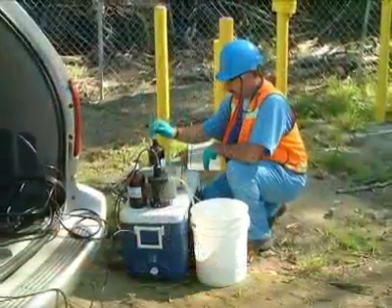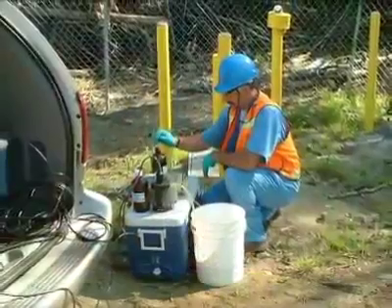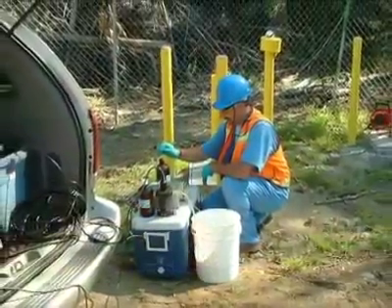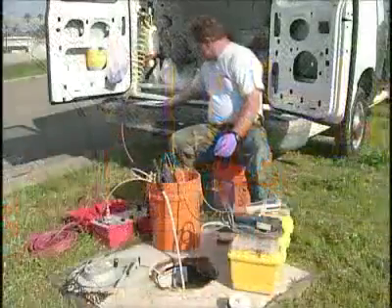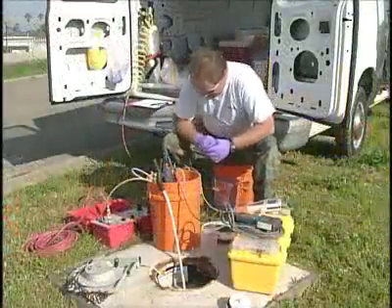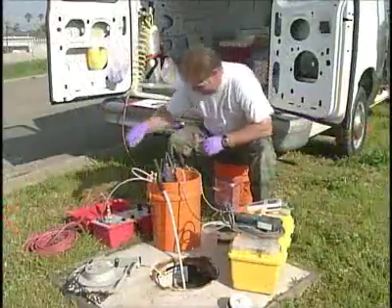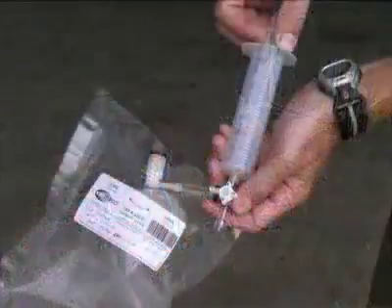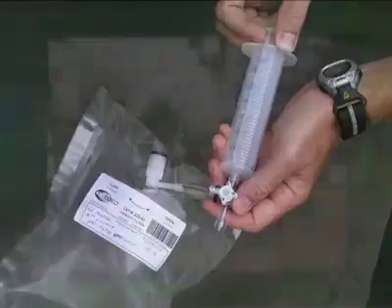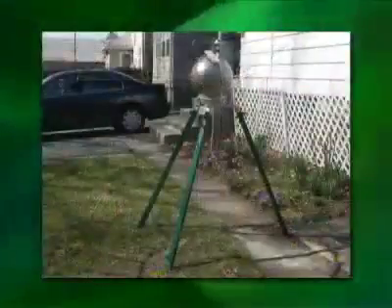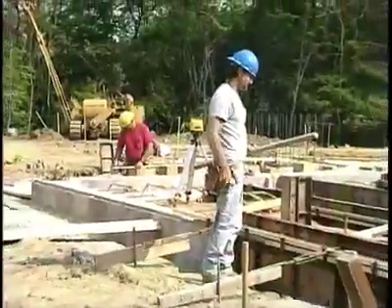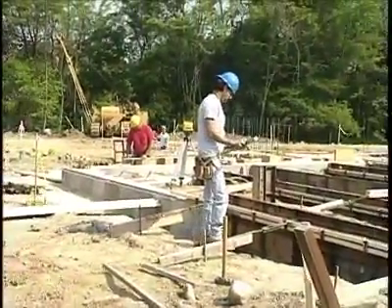Increasingly, reliance on a single approach or a single type of sampling is not considered adequate to determine the potential for vapor intrusion at a particular site. The current approach is to collect and evaluate multiple lines of evidence to better define the nature and extent of vapor intrusion. These lines of evidence may include groundwater, near-slab soil gas, sub-slab soil gas, crawlspace air, outdoor air, indoor air, building construction, or site geology.